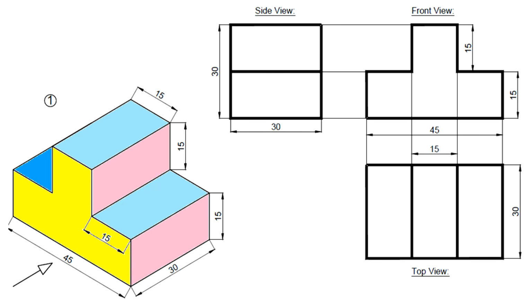So I am assuming the vertical plane here. These dimensions are 45 and 15, 15 and again 15, 15, 15, 15, 15. So this inverted T shape I can draw in the front view, and that is on the vertical plane. So I will be drawing 45, 15, 15, 15, and then I will complete this front view. Then above this view I will also write that it is the front view, and I need to give the dimensions.